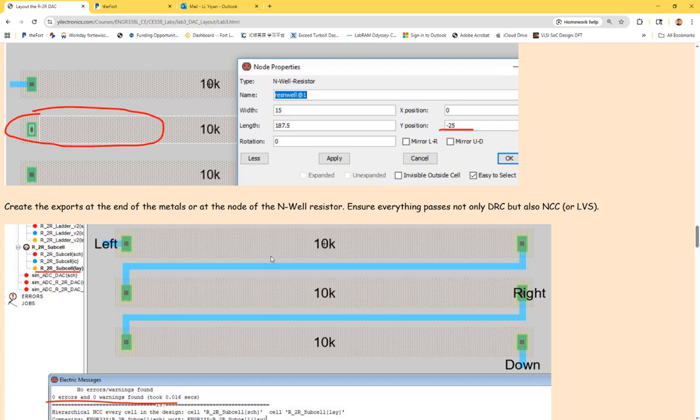So you can open up the chip, and you can see metal 3 physically when you receive the die, you can really see it, right? And then you use a wire bonder to bond the metal wire to that metal 3. That's how that works. Eventually, you can really communicate with the outside world by doing that, okay? So metal 3 is actually the metal that communicates with the outside world.